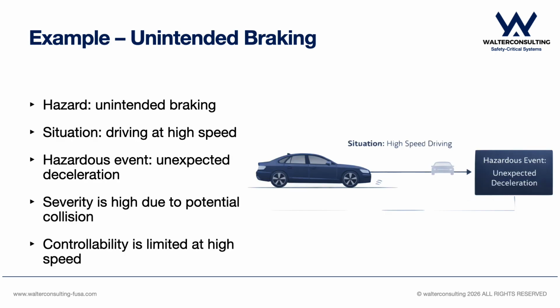Consider unintended braking. This is our hazard. Now let's define the situation. The vehicle is driving at high speed on a highway. If unintended braking occurs in this situation, the vehicle may decelerate unexpectedly. This creates a hazardous event.